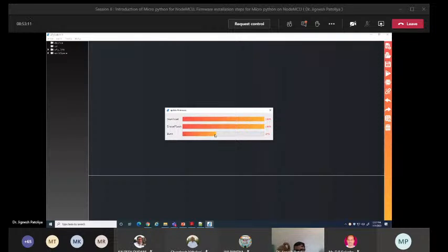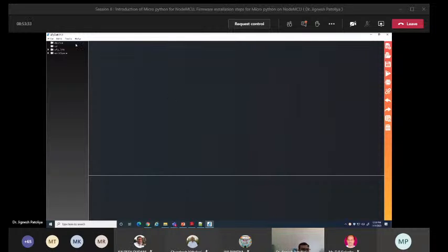So this binary code 0101 is being written in this NodeMCU, or sorry, flash memory, through this chip or through this USB to TTL converter. So it requires hardly 2 to 3 minutes, depending on your internet. Okay, once done, click on Tools, Serial, COM4, and once you select this COM4, see here, the terminal is there.